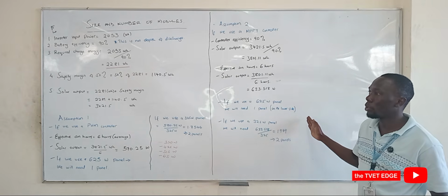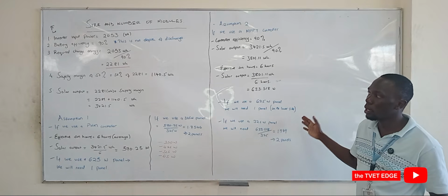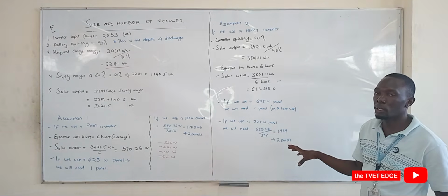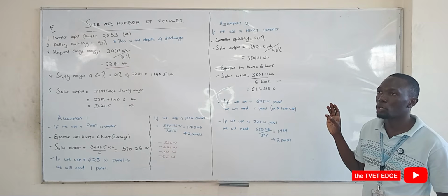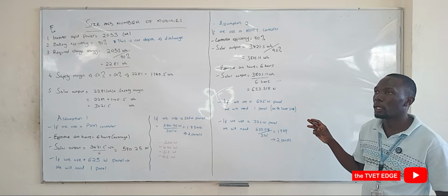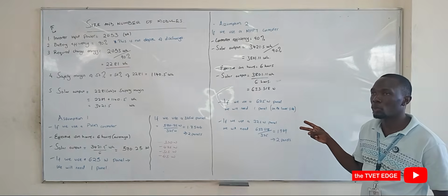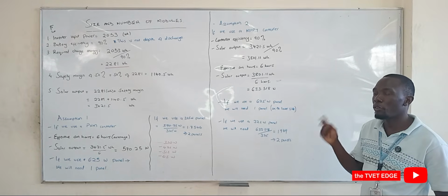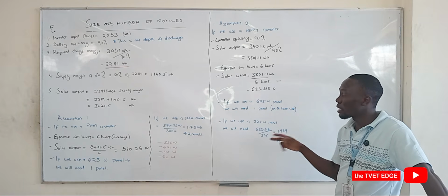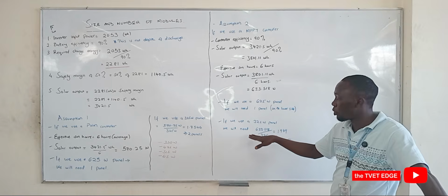And if you're going with the modern day components, for example, you will combine this with the already existing components, for example, with a 20 amp charge controller on the higher side. And our inverter was 1 kilowatt inverter. If you go with a smart inverter or a more advanced inverter, the inverter has got an inbuilt charge controller that will do this for you.